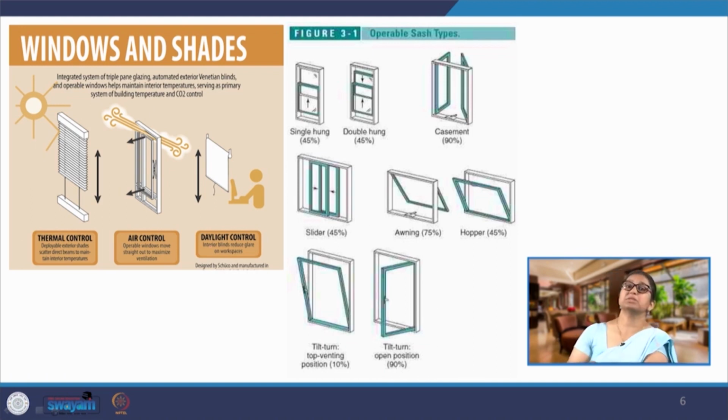But of course, the moment we say that, we also have to see that there has to be an integrated system where the system senses and identifies, or if manual controls are being provided, the air conditioning system is automatically stopped and only natural plus mechanical ventilation is provided. This will happen only in case a thermally comfortable environment prevails outdoors. So, we have to provide windows which are openable in buildings, if not all, then strategically some windows, which can be opened manually, and manual overrides have to be provided over the program that has been provided for operations.